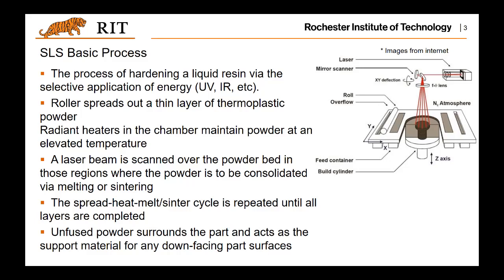A leveling roller will spread out a thin layer upon the existing layer. The laser beam will scan over the powder bed, and the region to be scanned will be solidified. Once one layer is solidified, the whole platform will move downwards by one layer thickness.